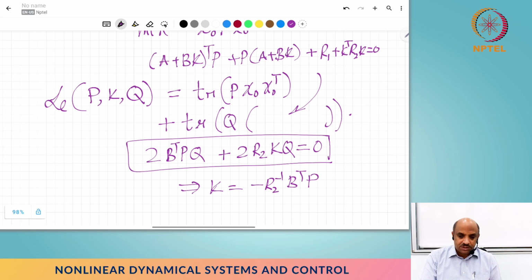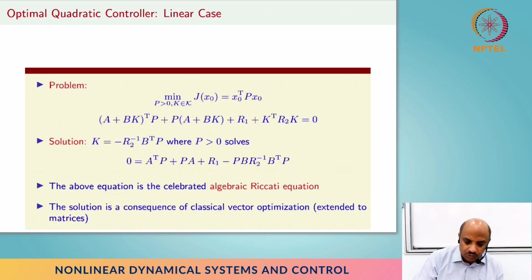So under what conditions can Q have positive definiteness and things like that, and we can actually show certain things about this formulation by setting the derivative with respect to P, and we can show that that will be actually an equation that involves a similar equation, but it's an adjoint equation, and because A plus BK is already assumed to be stable, Q is going to be positive definite and things like that.